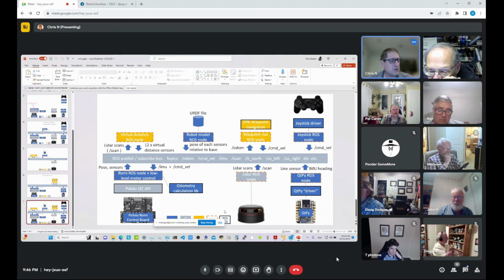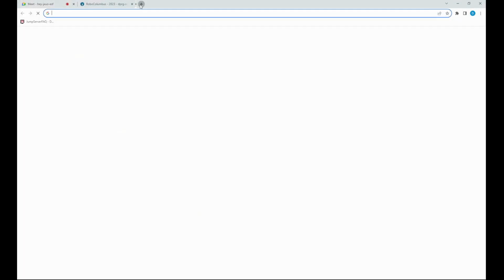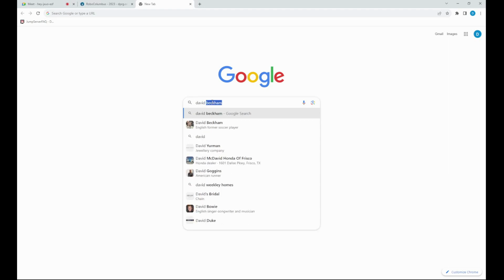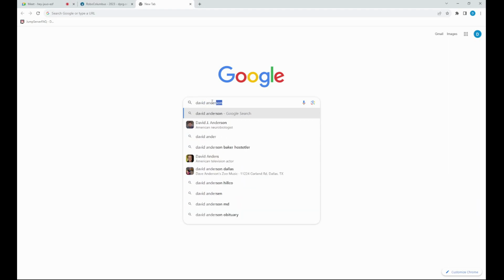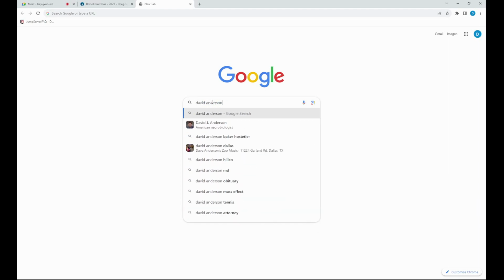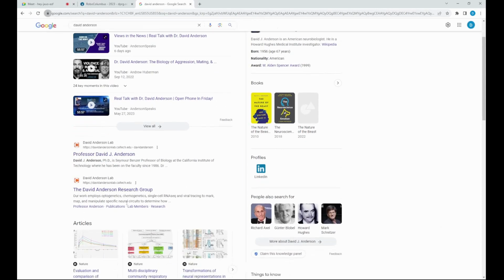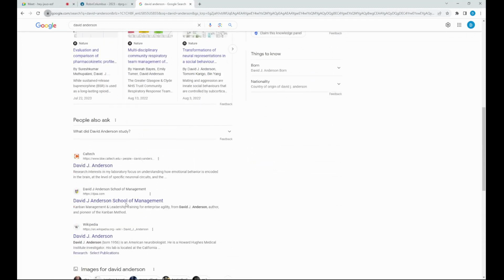He's doing standard odometry, but in some versions of his robots, when he has IMU data, he's simply pulling in the heading from another sensor and plugging that into the standard odometry calculations, rather than letting that error accumulate as much as it usually does with pure wheel encoders.